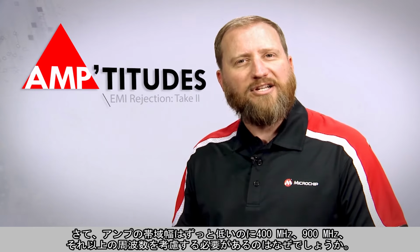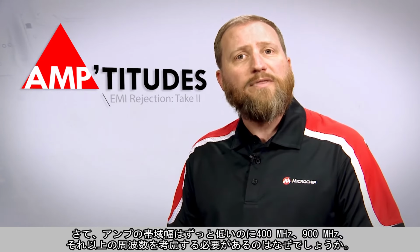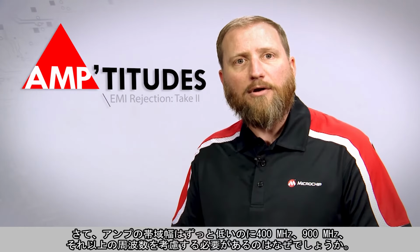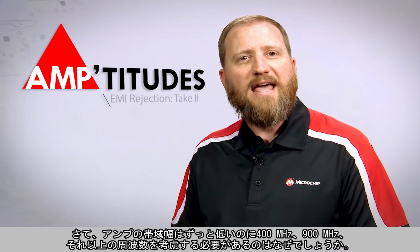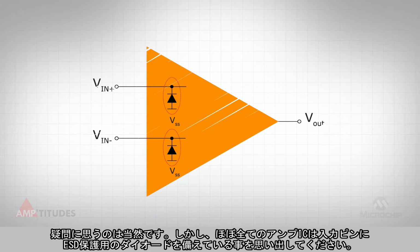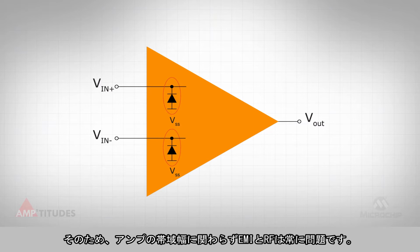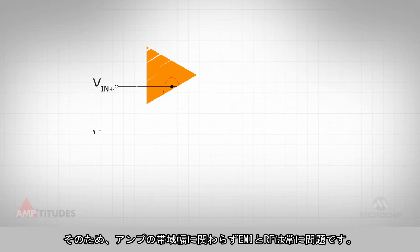Now, one common question that we get is why be concerned with high frequency, perhaps 400 megahertz, 900 megahertz, and higher, when working with amplifiers that have a bandwidth well below this range? This is a very reasonable question, but keep in mind that virtually all integrated circuit amplifiers have ESD protection diodes on the input pins. These diodes can rectify these high-frequency signals, causing a shift in the input signal. Therefore, EMI and RF are always a concern, regardless of the bandwidth of the actual amplifier.